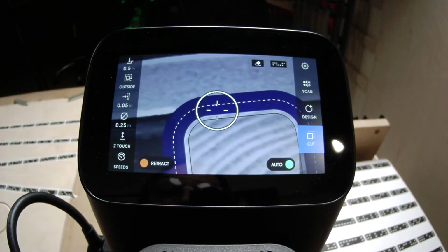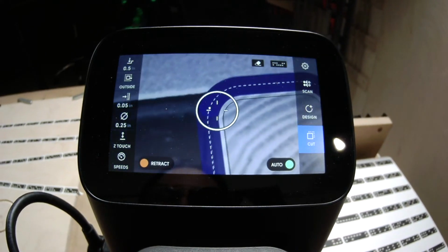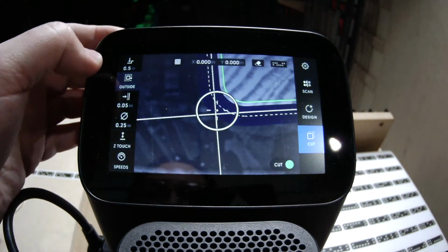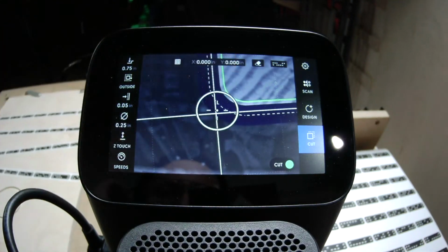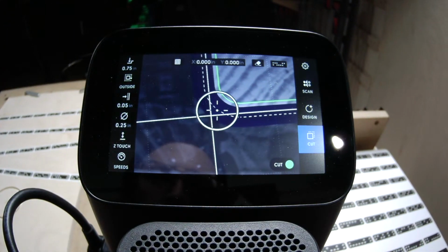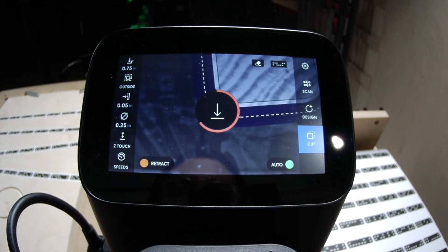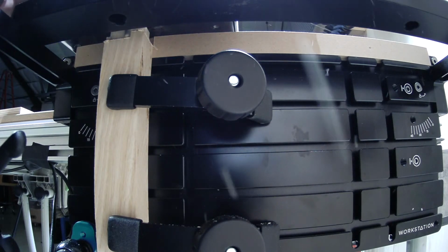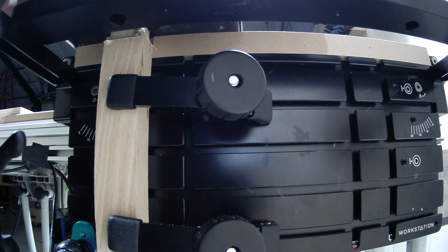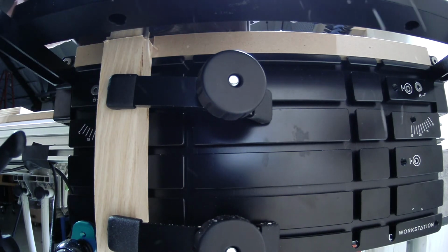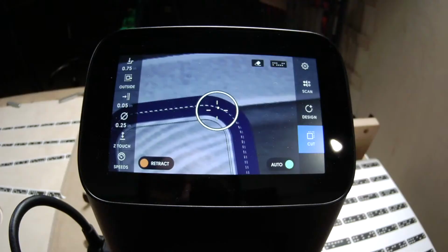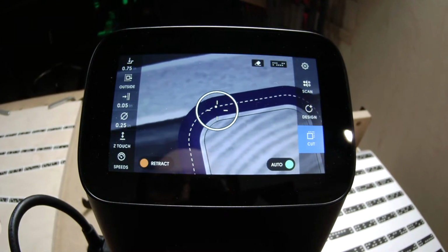If you're unsure what the standard speeds are when you get started, you can press and hold the green button down, and that'll move the unit at a very specific speed. It's set up for the basic speeds of cutting plywood with a 1/4 inch bit. Obviously you can change that in the bottom left with the speeds option, but we're coming around the third pass here. So now we're 3/4 inch deep with offset still applied. We're going to go around this one more time, and then for the last pass, we're just going to change the offset to 0, and then we'll finish up.